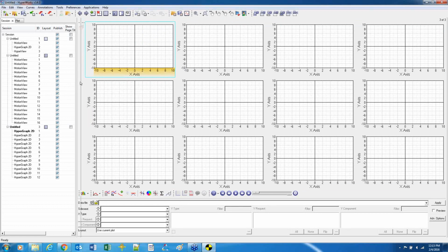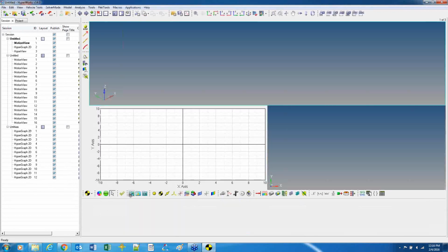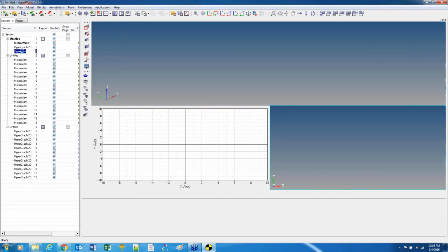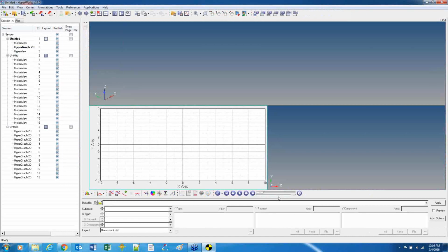And you'll see that when we get a little deeper into the reports in the demo. So as with many codes, you have your menus across the top, your various toolbars for visual and quick access to certain features, and then down here we have a toolbar set that is dependent on which window type you're in. So if I go back to MotionView, this bottom toolbar changes to everything involved in the pre-processing. If I go to HyperView, this toolbar changes to all the visualization options for your animation, and then HyperGraph, again, it's the toolboxes for all of the plotting.